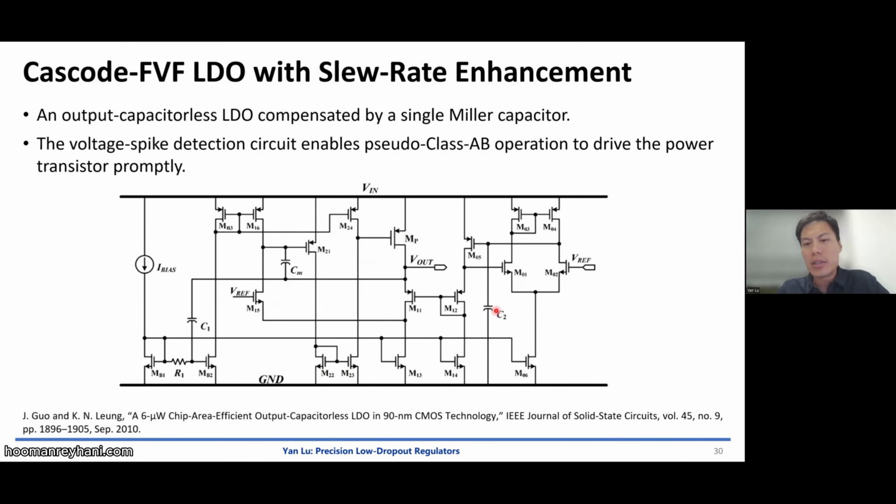On the right, it's the DC biasing circuit that generates what we call reset. Here's the reset. And the Vref, the reference voltage, is here to generate V mirror and reset. For this local feedback, for the low frequency local feedback, we have a C2 connected to ground that defines the dominant pole of this DC loop, not this low frequency loop.